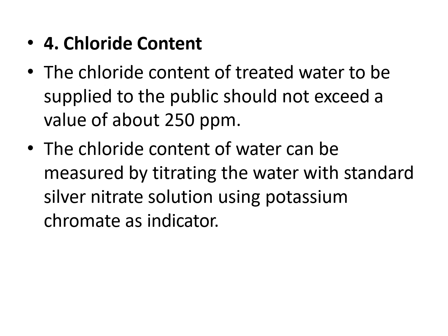Then chloride content. The chloride content of treated water supplied to the public should not exceed the value of 250 ppm. The chloride content of water can be measured by titrating the water. The standard solution to titrate the water is silver nitrate solution. The indicator is potassium chromate.